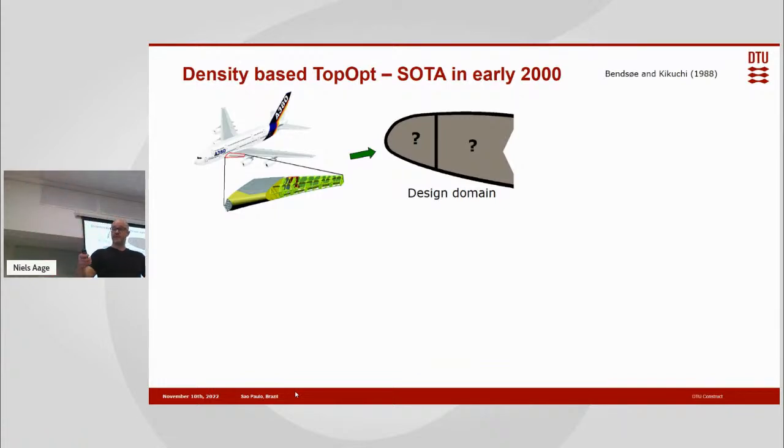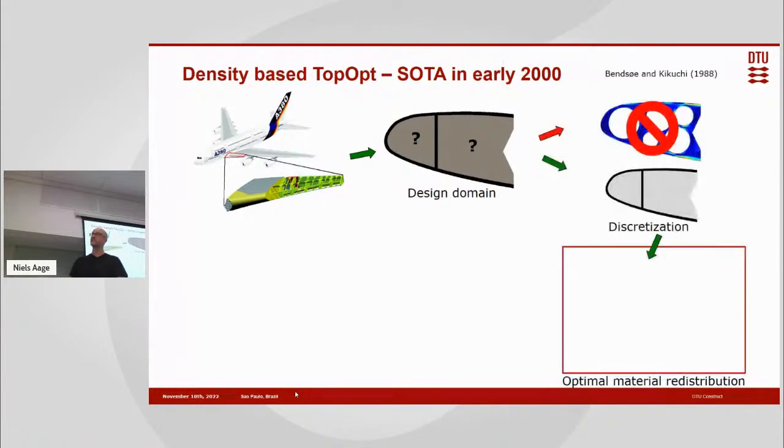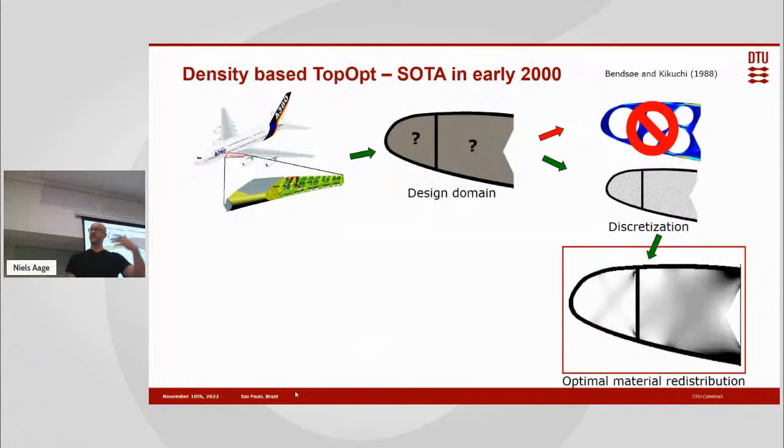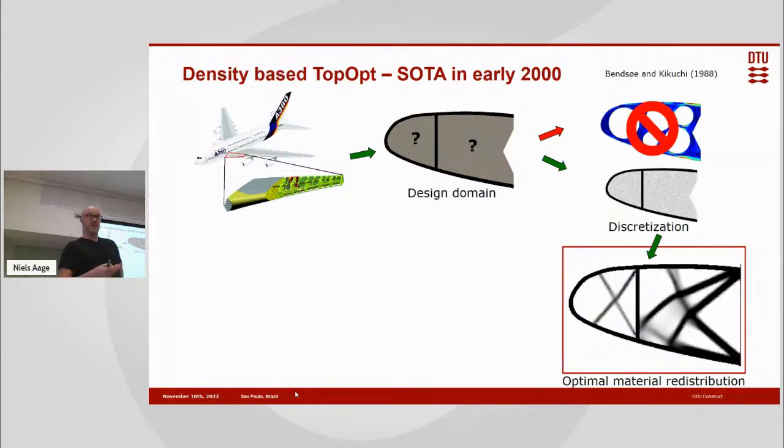One of the groups, consisting of around 40 engineers, works only on this small part of the wing, the leading edge. They took every rib out, removed the material, and did the topology optimization thing, which, to non-mechanical engineers, means no round holes, not good for stresses. So they did a discretization and started the optimization process. As you see, out of nothing comes definitely not round holes, but a nice structure consisting of some configuration of straight bars, best for transferring loads in tension and compression, no moments.